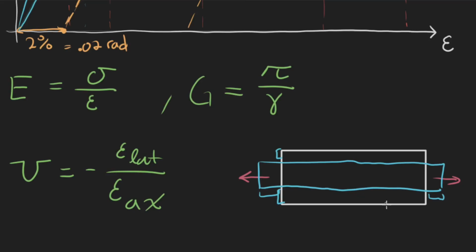And then for something that's very elastic like rubber, you're going to get pretty close to 0.5, which comes from the conservation of volume, which technically isn't a thing, right? I could pack something in so that it has more density, but if you assume conservation of volume, the maximum Poisson's ratio would technically be 0.5.